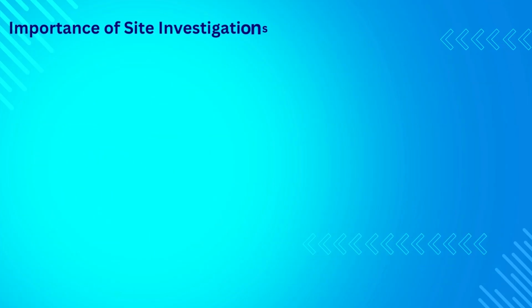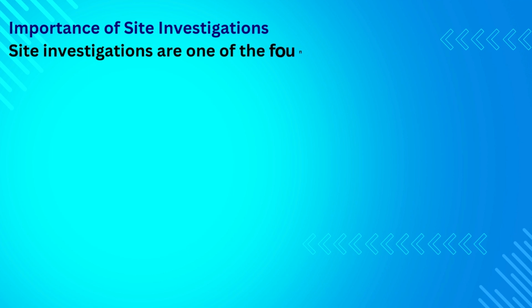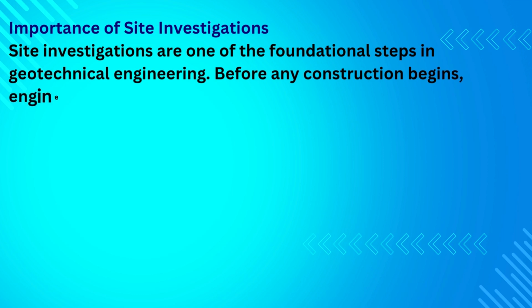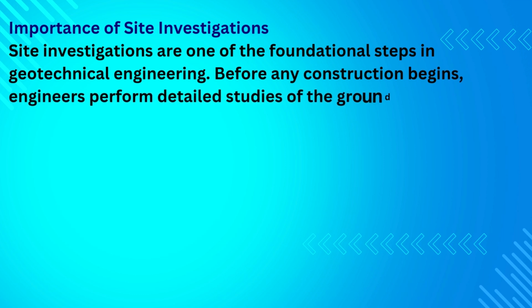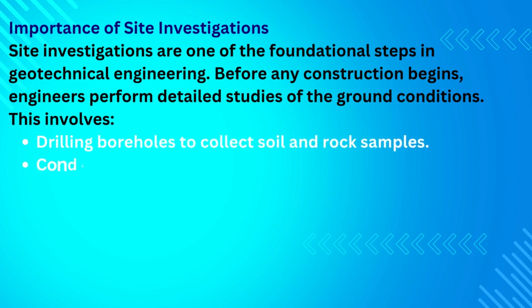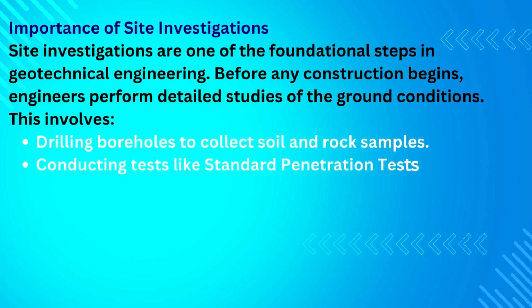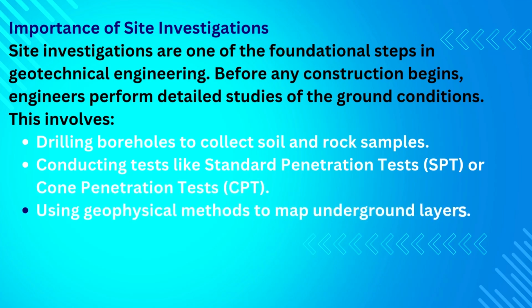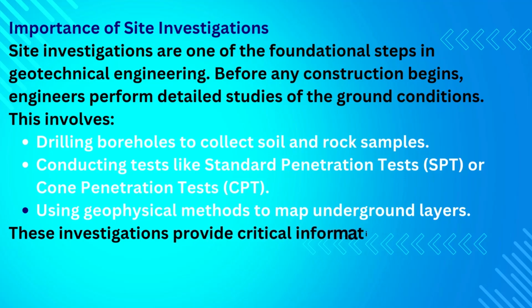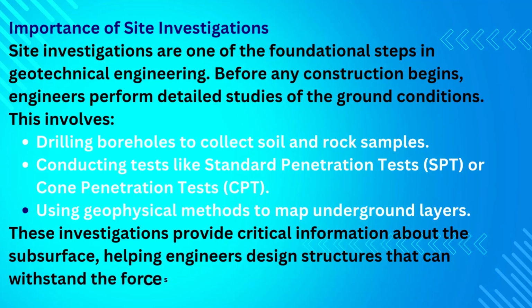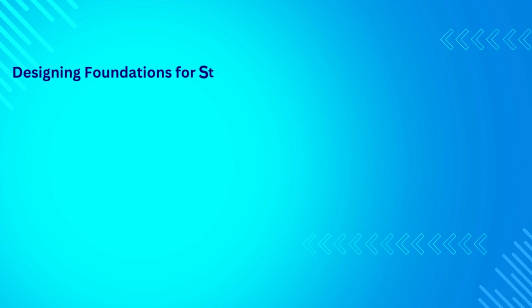Importance of site investigations. Site investigations are one of the foundational steps in geotechnical engineering. Before any construction begins, engineers perform detailed studies of the ground conditions. This involves drilling boreholes to collect soil and rock samples, conducting tests like standard penetration tests, SPT, or cone penetration tests, CPT, and using geophysical methods to map underground layers. These investigations provide critical information about the subsurface, helping engineers design structures that can withstand the forces of nature and human use.